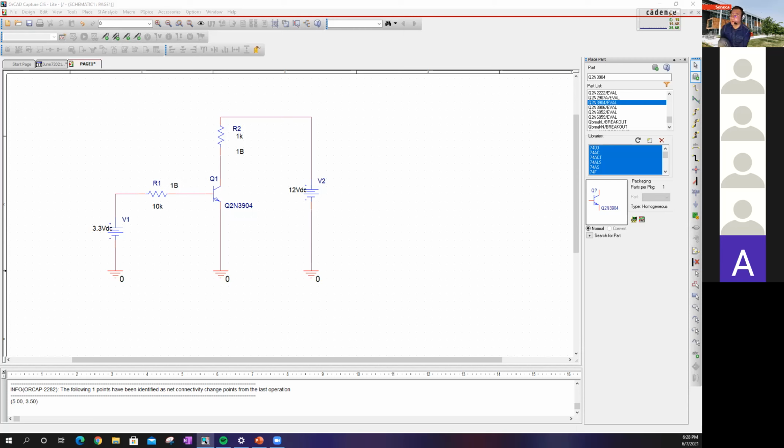Yeah, you're perfectly right. This is one of the more advanced concepts, and I think Prakash might have already gone over it. The IC cannot be higher than the circuit limitations, because our V is only 12 volts. The circuit limitation for IC will be VCC divided by R2 in this case, as you see on my screen here.